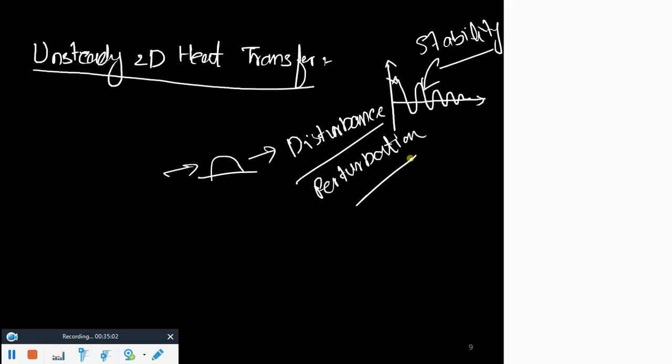Okay, so this is disturbance or perturbation. Why? Because the vehicle has been disturbed from its initial state. Now the problem is, before coming on to this speed breaker, the vehicle was initially at y equals 0, for example. Obviously it is moving in x, but y was 0. And after going through that perturbation, would you be able to achieve y equals 0 once again or not? If you are able to achieve that, it means your system is stable.